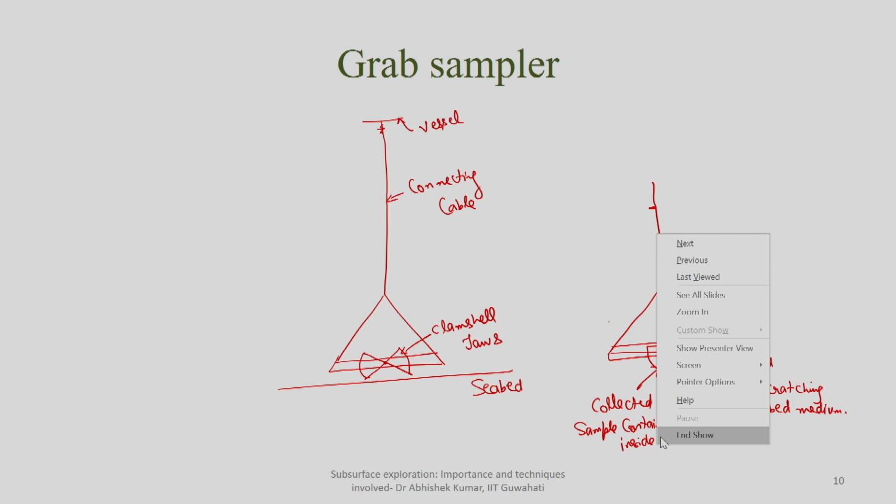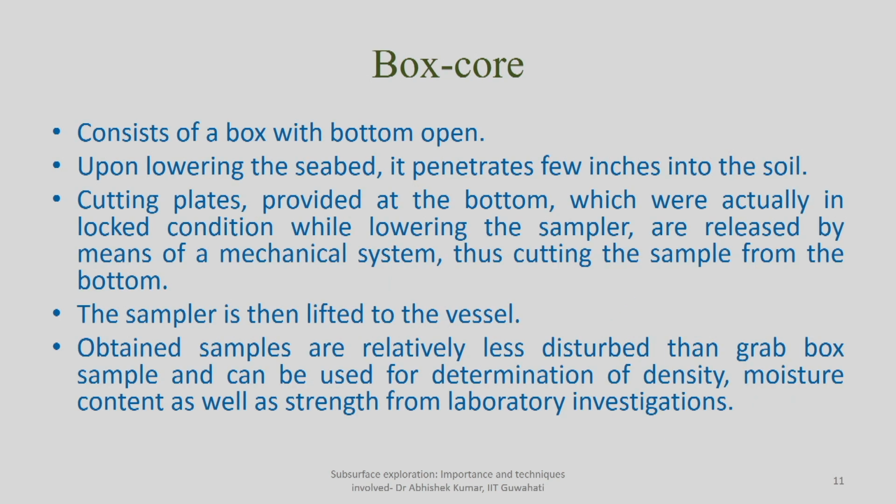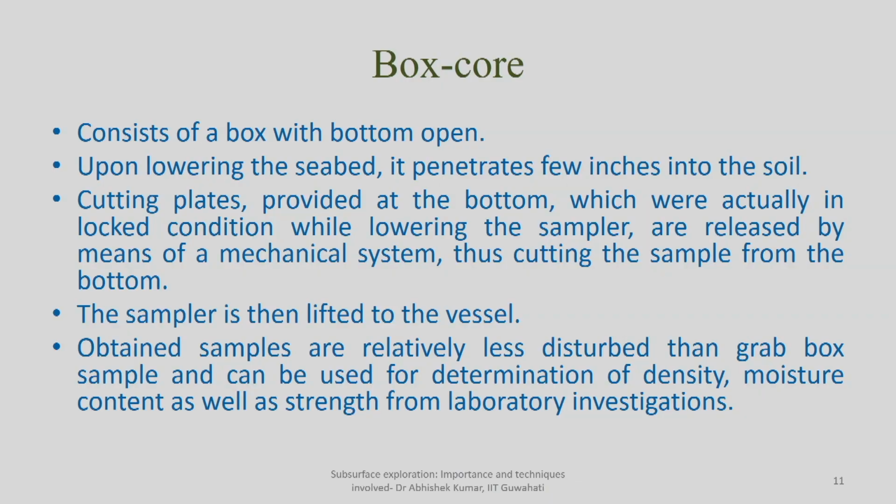Now, let us see the box core. Again, as I mentioned, the fundamental concept remains the same: each of these collects the sample from the seabed by means of one or the other arrangement. The box core consists of a box, as the name suggests, with an open base. So the bottom is open. Upon lowering the box, when it touches the seabed, it penetrates into the seabed material.